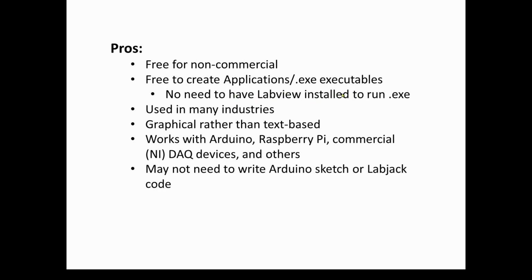So it's really nice. You can generate a project in LabVIEW, create an executable, put it on a thumb drive, bring it over to another computer that doesn't have LabVIEW, and it can do data acquisition for you using your LabVIEW project. Really wonderful. So again, as we said before, it's used in many industries. And for many people, a really big positive is it's graphical rather than text-based. You don't have to write lines of code. You just drag and drop and wire up the different components.